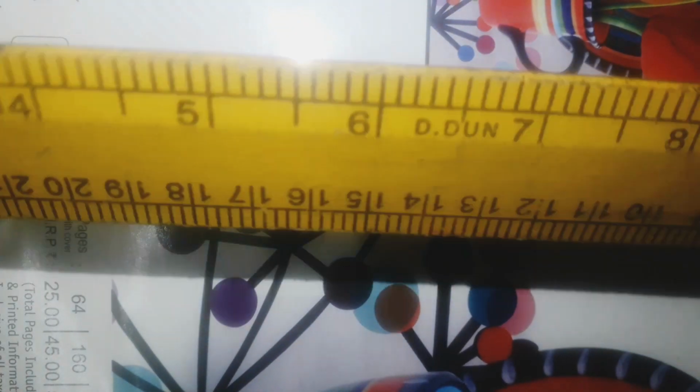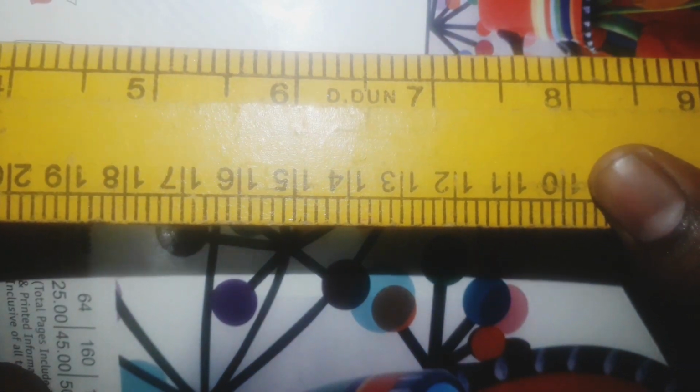If you take the scale, you see here, I can bend the scale like this. If I apply a force here, I am able to bend it, but I cannot bend the scale when I apply a force here. Because when you keep the scale like this, it is this thin material which gives me the resistance. But when the scale has the orientation like this, the entire thickness will give me the resistance.